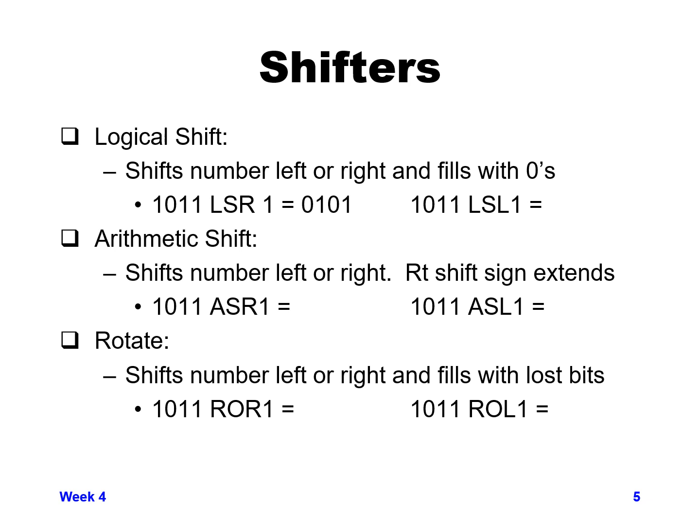Now, when we do a logical shift left, again, everything will shift to the left. We'll lose the leftmost bit completely, and we fill the rightmost bit with a 0. So in this case, we're left with a 0, 1, 1, and then the new bit of 0 that got filled in.